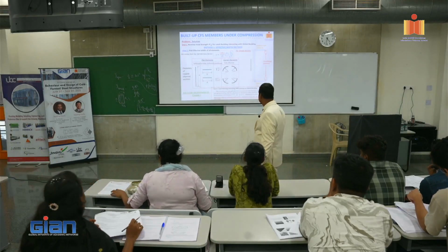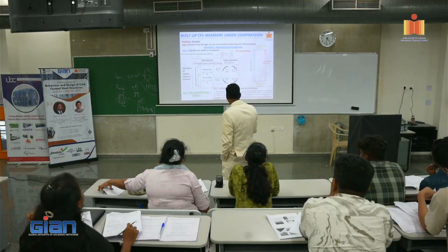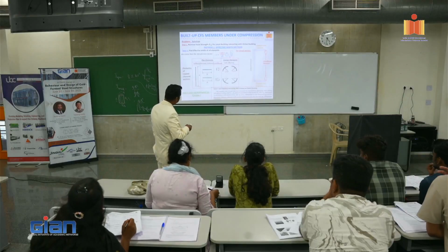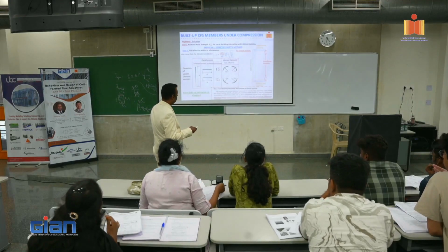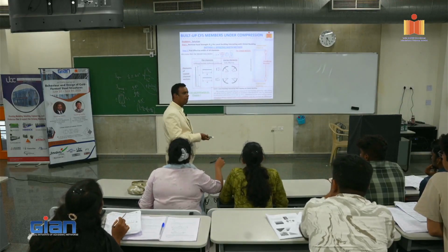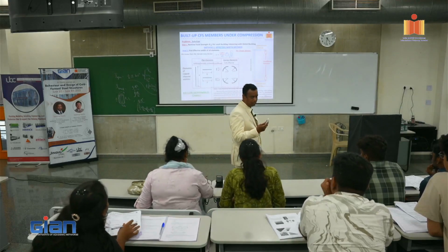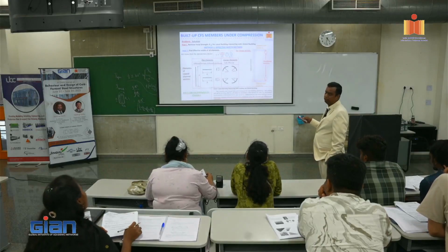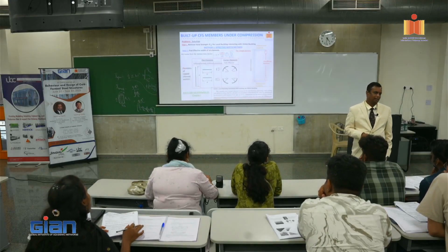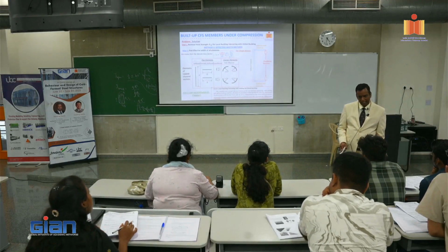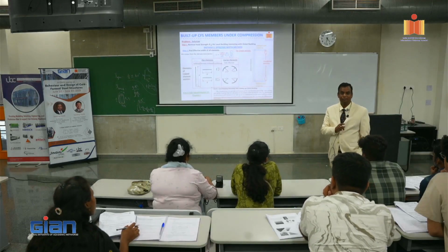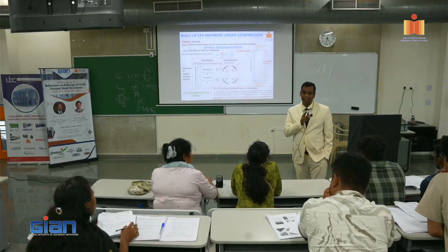Next, what do you need here? This one is the t. Thickness is the base metal thickness, which we know. Fn we have already calculated in the previous one, the nominal. So we need everything; the only unknown is k. What is k? Plate buckling coefficient. Elastic plate buckling coefficient. Don't say just plate buckling coefficient; it is the elastic plate buckling coefficient.